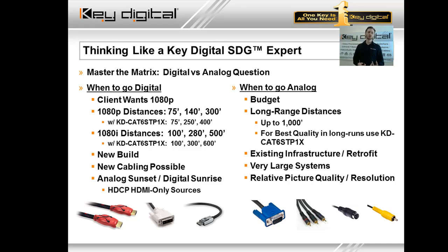Now, we in the industry, in the video side of the industry especially, have what I would consider to be a critical eye, trained eyes, knowing what to look for that are the indicators that this picture is of good quality. For example, the question of 720p versus 1080i, that especially is going to be something that's relative. As we've discussed, the bandwidth is comparable. It's just a matter of, do you want more horizontal lines of resolution but only get every other picture and have it alternating, or do you want a progressive picture with every line